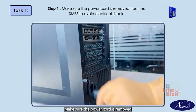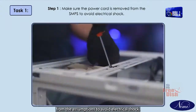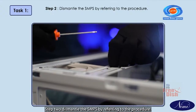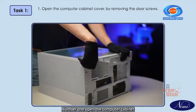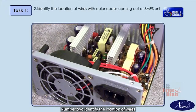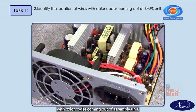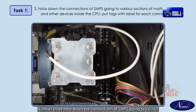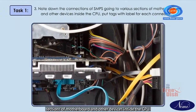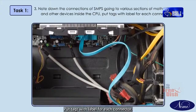Step 1. Make sure the power cord is removed from the SMPS to avoid electrical shock. Step 2. Dismantle the SMPS by referring to the procedure. Number 1. Open the computer cabinet cover by removing the door screws. Number 2. Identify the location of wires with color codes coming out of the SMPS unit. Number 3. Note down the connections of the SMPS going to various sections of the motherboard and other devices inside the CPU. Put tags with a label for each connector.